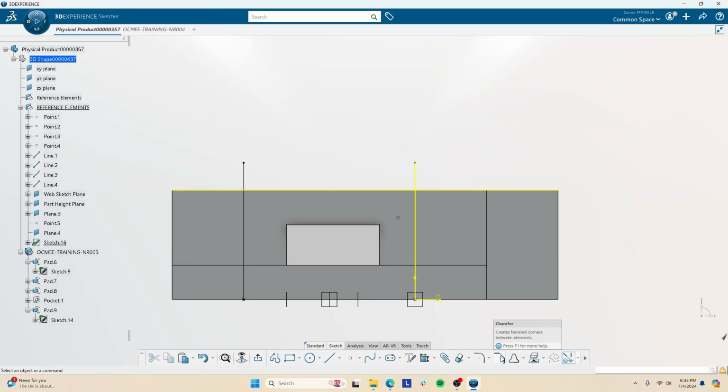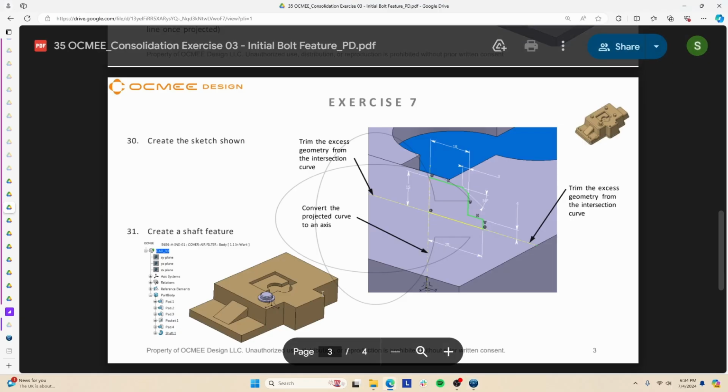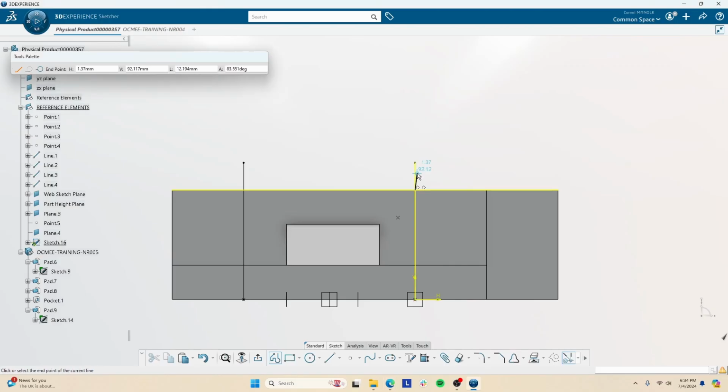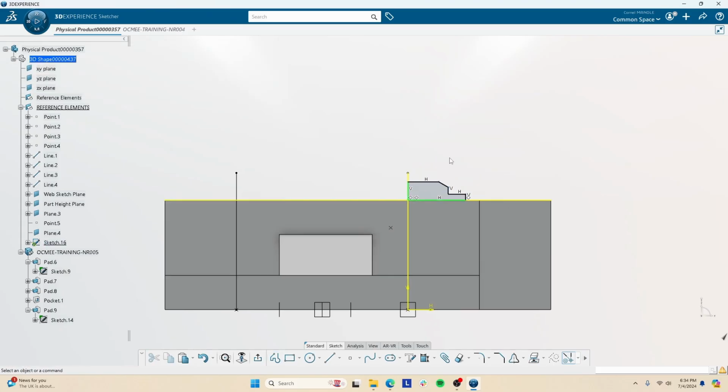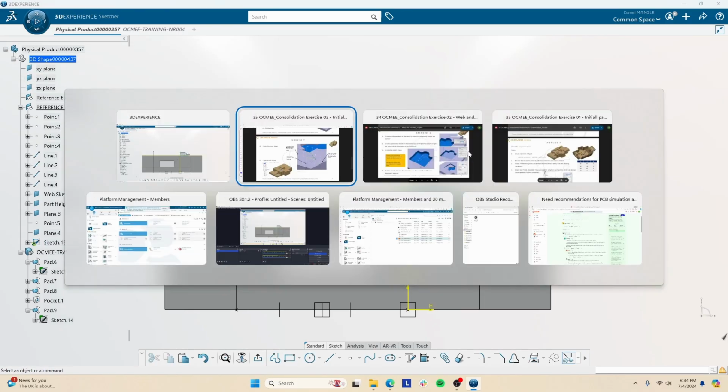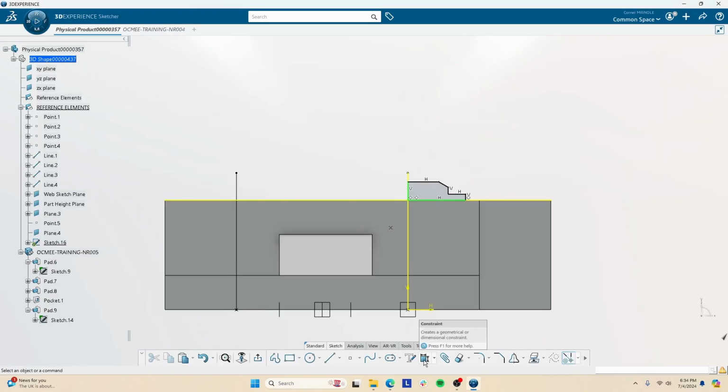Now there is a chamfer tool, and I guess I'll show you that way, but it doesn't really define the dimensions too well. So actually I'll just create a different kind of profile. I'll manually create like a little chamfer here myself. And you could also do it after modeling this part. You could do it in the actual 3D body instead of the sketch, but again, we'll follow this for now.